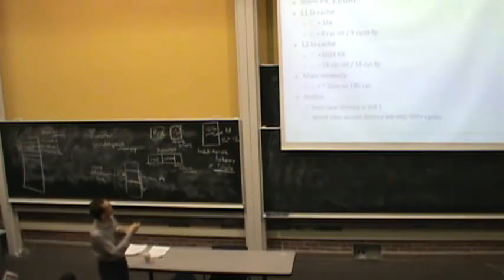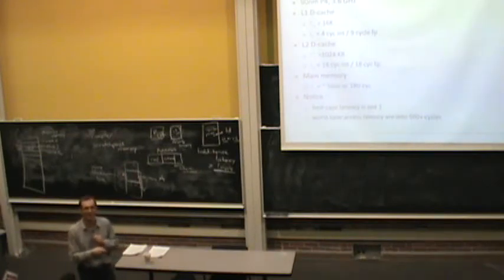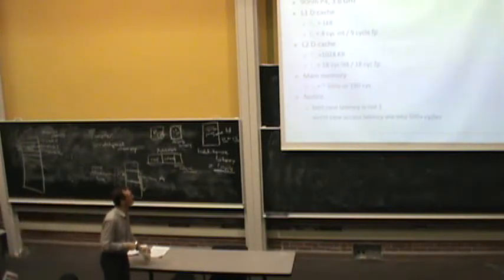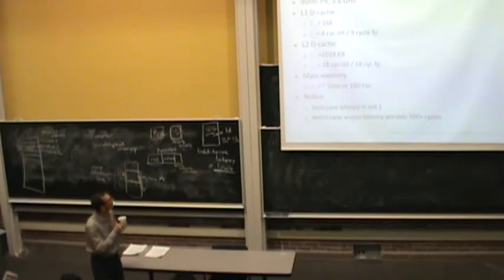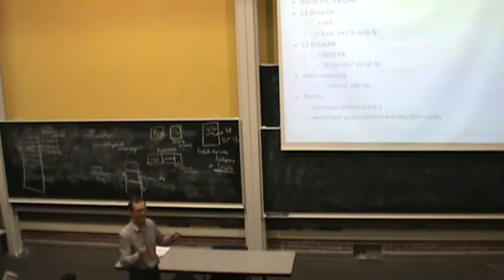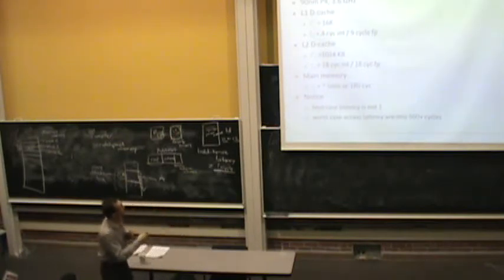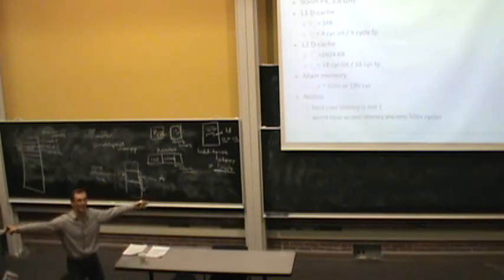So if you look at Pentium 4, I will not go over this a lot, but I'll give you some parameters from a reasonably recent processor, but still, how many years old? 15 years old, maybe? Or almost 15 years old, at least that's when the design started. Well, this is Prescott. This is a 90 nanometer version of Pentium 4, so I'm not that much of a dinosaur yet. So if you look at Pentium 4, you have a D cache that's 16 kilobytes, and its access latency is 4 cycles, for integer operations at least. FP operations take longer because they access wider data.